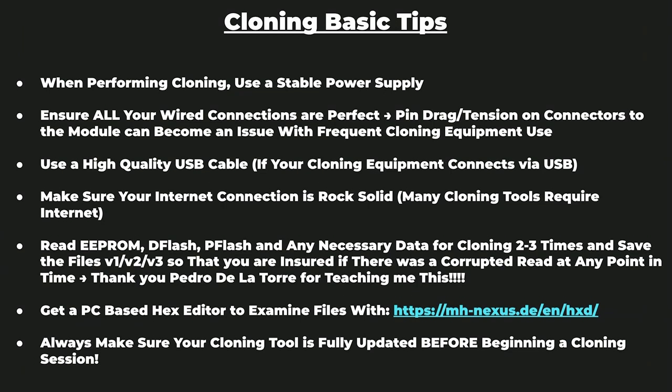Here's some basic tips on cloning. You just want to keep these in mind when you're going to do any module cloning. We always want to be triple checking all of our connections to the modules. We want to make sure that our pin tension is good on our connectors. We want to make sure we use a high quality USB cable. Check your USB cable that you're using between your MDCI and the T-Ninja Box Y cable. You want to make sure your internet connection is strong. Sometimes you have to have an internet connection to perform a cloning function.